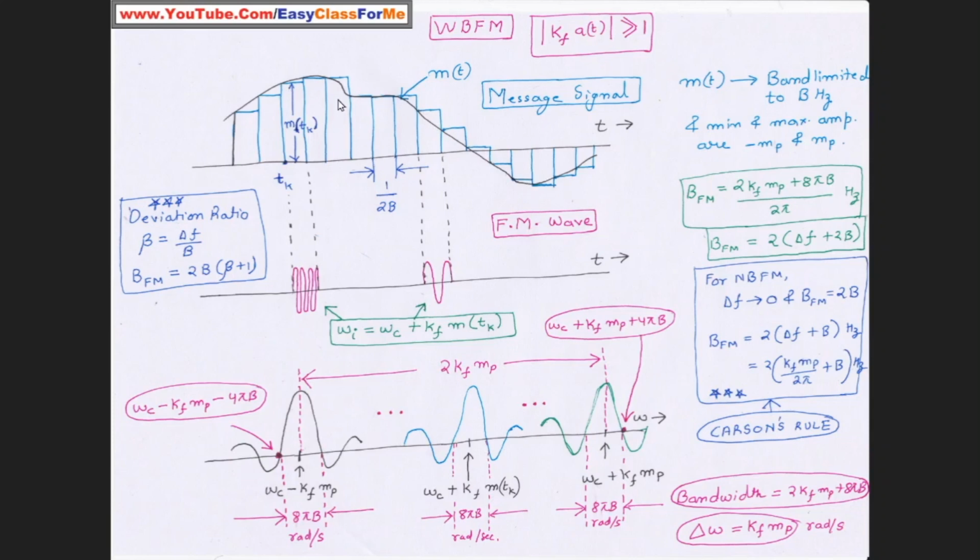And had this diagram been the diagram of a frequency modulated wave, we can already see that for this particular staircase approximation, since the value of amplitude is high here, you will have a high frequency signal here. That means in addition to the carrier frequency, there will be an additional frequency, as we know from the equation of frequency modulation. So this is high here, and since here the amplitude is low as compared to this one, we will have a relatively low frequency here as compared to the carrier frequency.